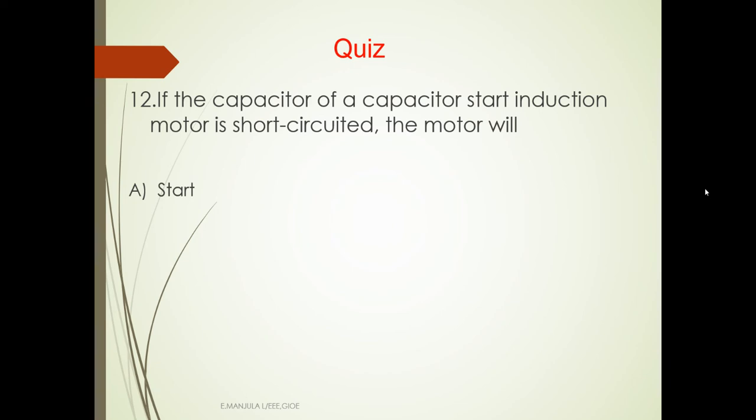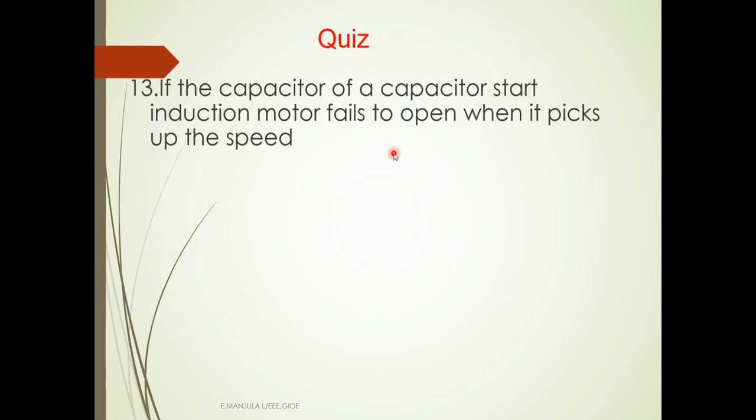So it won't start. If the capacitor of a capacitor start induction motor is short circuited, the motor also does not start.